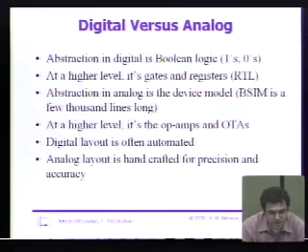BSIM, as most of you know, is basically a standardized model that has hundreds of parameters that describe the transistor behavior. And these parameters are given to you by the fab, the person who fabricates your circuitry, characterizes these transistors and describes them. Instead of giving you raw data, they give you BSIM models or BSIM model parameters. And your simulator knows how to interpret those parameters and can simulate circuits for you. Now, BSIM actually has a long history. It started here in Berkeley. In fact, the B in BSIM does stand for Berkeley.